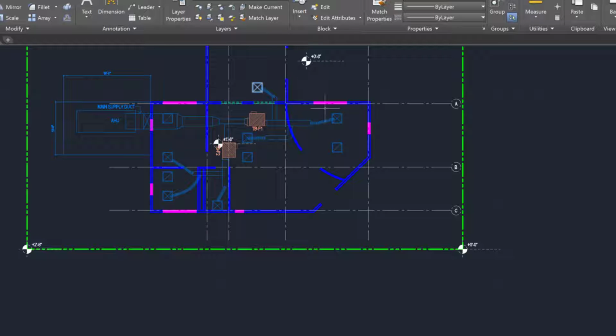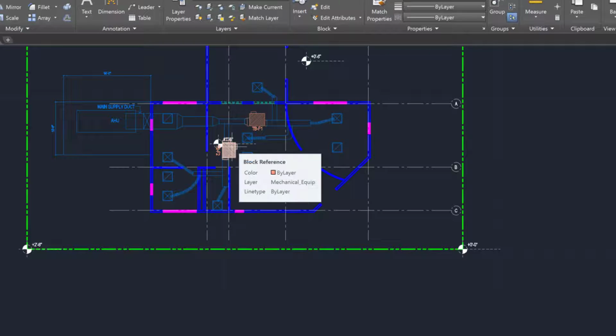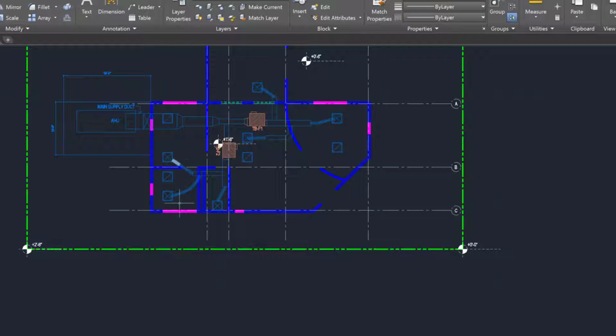So this will become one air system, and then we'll select this as an equipment that will be supplying air to these 3 diffusers. Then we'll create another system in which we'll have these 3 diffusers, and these 3, then we'll select this as equipment which will be supplying air to these 3.